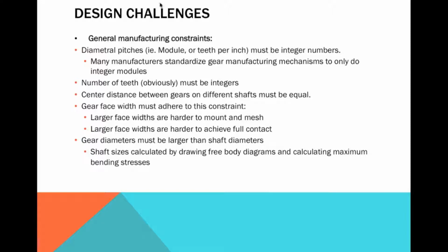The number of teeth, obviously, has to be an integer. You can't have 30.2 teeth on a gear. This won't work. The gear has to have a whole number of teeth all the way around. The center distance between gears on different shafts must be equal.